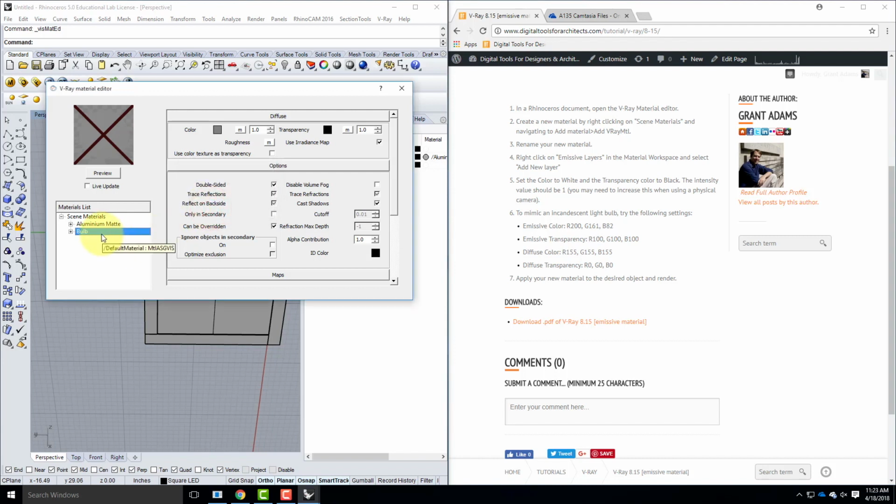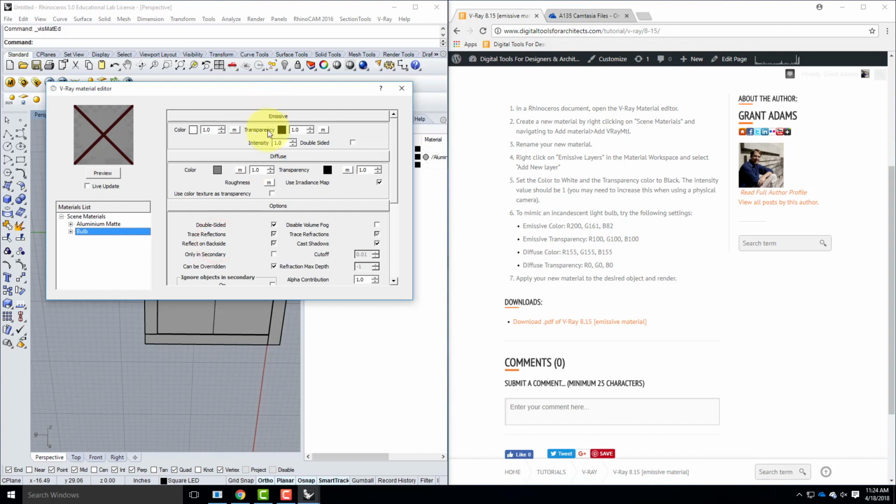There it is. Next thing I need to do is right-click on the bulb layer, and go to Create Layer, Emissive. So we've done reflection and refraction before, but we haven't done emissive. And what emissive means is that this is a light-emitting material. So if you wanted to create any kind of neon or glow-in-the-dark material, that's where it comes from, this emissive. So I'm going to create the emissive layer, and you see that in the drawers I added a drawer for emissive.